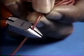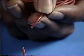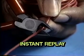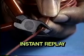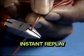The reason you turn the bevel down is to protect yourself and anyone around you. Cutting wire can shoot a piece of it several feet with considerable force, and someone could get hurt. Always observe safety rules in order to prevent accidents.